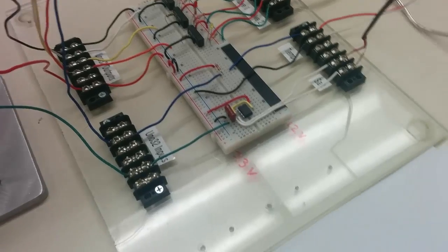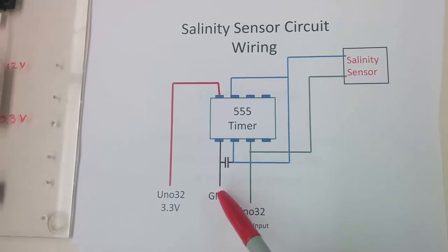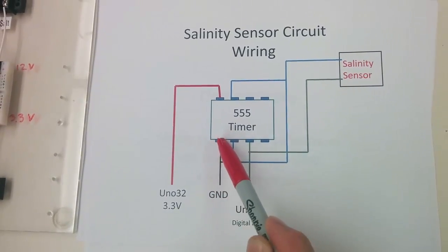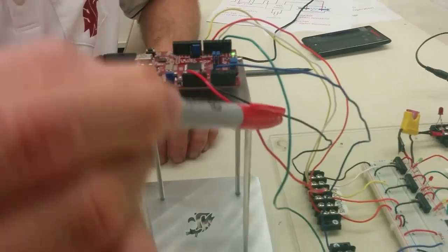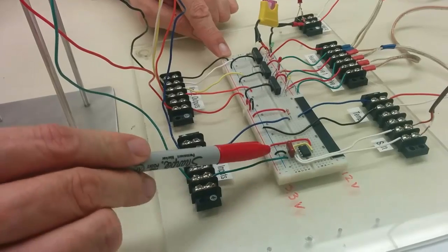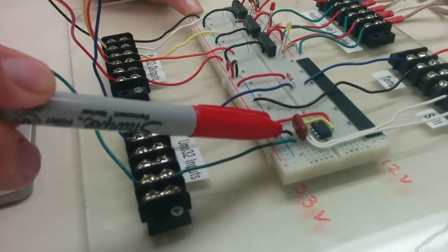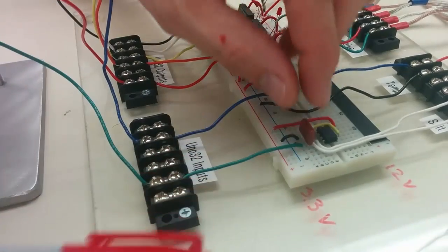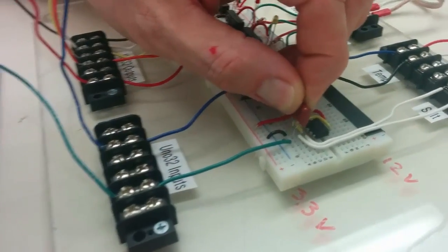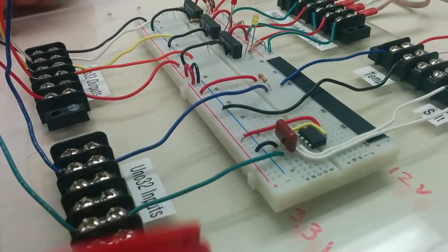Again, the ground is also coming in, so it's going to come off the UNO 32 and go to pin 1. So the ground, the black, comes over, jumps over to the rail here, and you can see this small black wire jumping to pin 1. Now, this capacitor is also installed next to pin 1, between pin 1 and 2, and then other wires here are made connections.